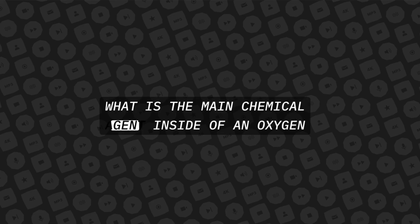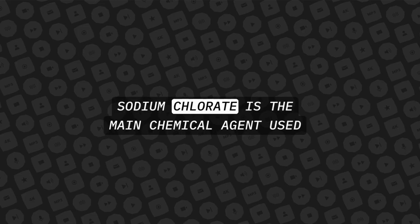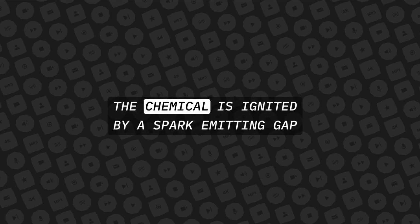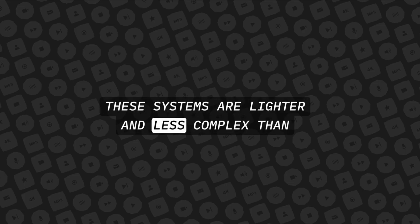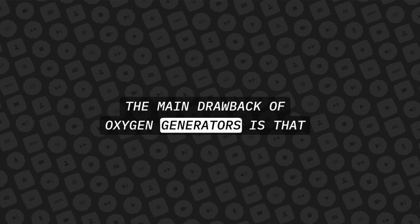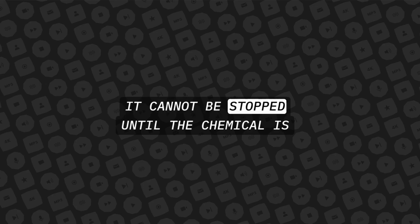What is the main chemical agent inside of an oxygen generator? Sodium chlorate is the main chemical agent used in aviation oxygen generators. The chemical is ignited by a spark emitting gap, and when it burns, O2 is generated. These systems are lighter and less complex than oxygen storage based systems. The main drawback of oxygen generators is that once the burning of the sodium chlorate begins, it cannot be stopped until the chemical is consumed.